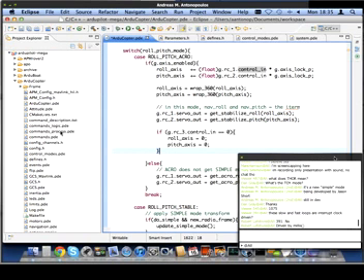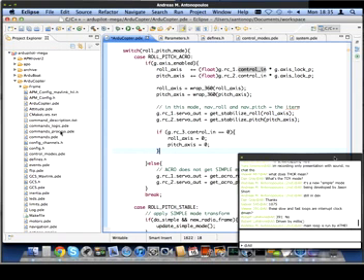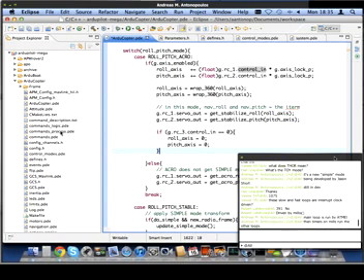So, just to recap here, what we're doing inside of the switch statement is we're looking at the roll pitch mode. We're decoding the user's input from their controller, which is being held in the RC1 and 2, which are the roll and pitch input from the pilot.